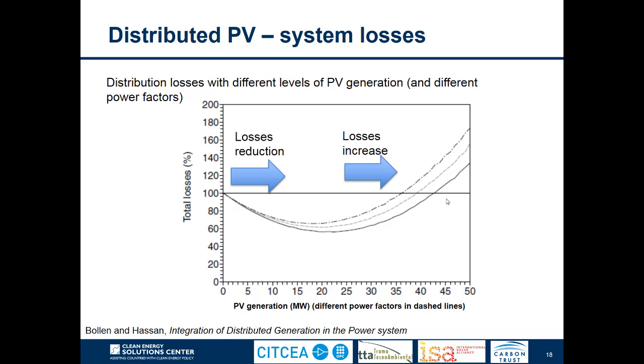Depending on the value of the reactive power, we can basically control the voltage at the point of connection of the solar inverter, and having the appropriate voltage and reactive power can also allow us to optimize the losses. So for each condition, we can see what the optimal condition of the solar inverter is and adjust the reactive power in order to reduce the losses in the network.